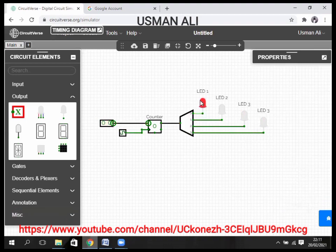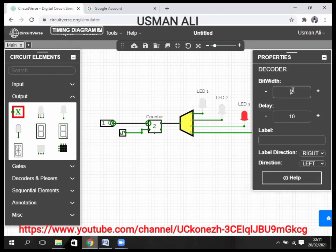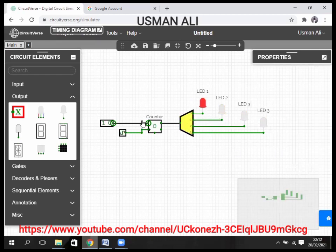You see it here, our first LED light is on. It means our circuit has just started. You see here, the bit width of our max value is 2. The bit width of our counter is also 2, and the bit width of our decoder is also 2. You have to place the bit width at the right number.